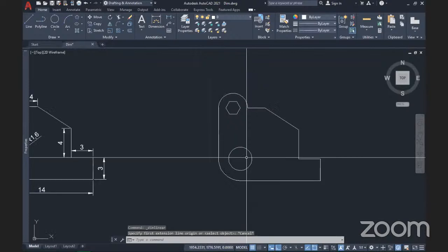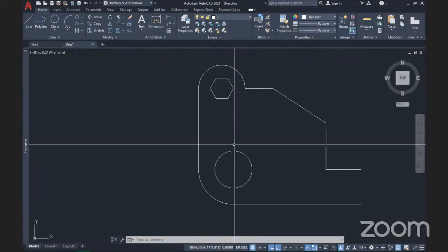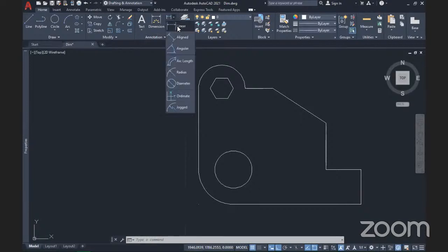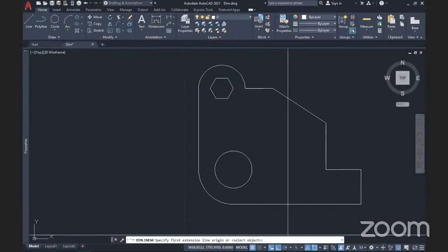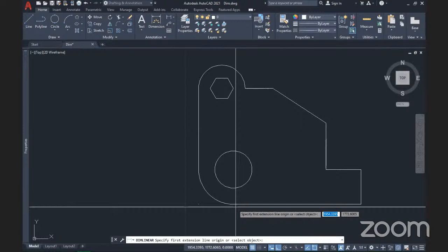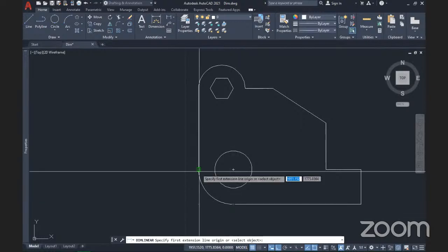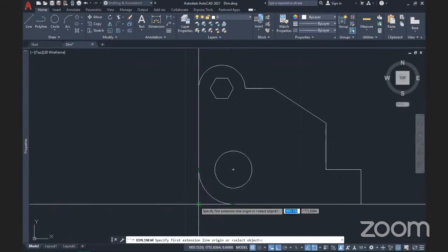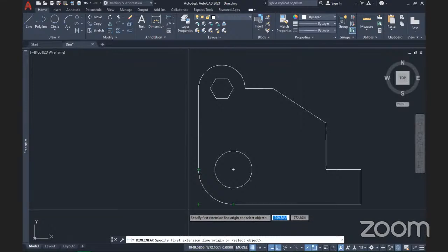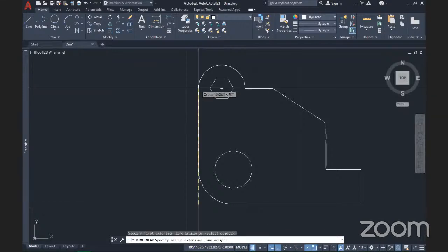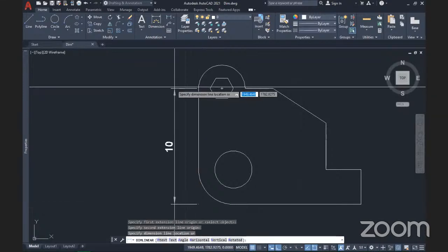Chizzy, you're welcome. You did not really miss anything. You can watch the video later to confirm what I just said. I'll just go to the linear measurements, click on it, and then, of course, the snap for node is turned on, so I can snap to that point I created by tracking this point and this other endpoint. Tracking this point and this endpoint gave me where I could place that point there. So having said that, I will just start here, click, and then click on my second point, and then drag to place my dimension line.